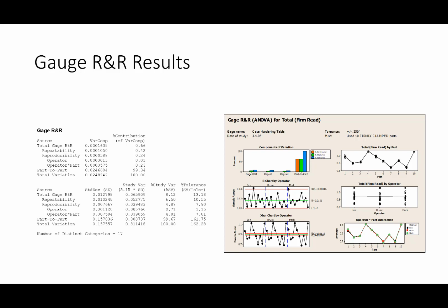The R chart and X bar chart show the special causes. The R chart should be stable and in control limits, which it is, whereas the X bar chart should not be stable because you want variability to be due to part variation, not measurement systems. And the result by operator should be spread out to show that neither one of the 3 operators selected had higher or lower values overall. And then the operator-part interaction, just like the part-to-part chart, should be closely grouped together in time series.